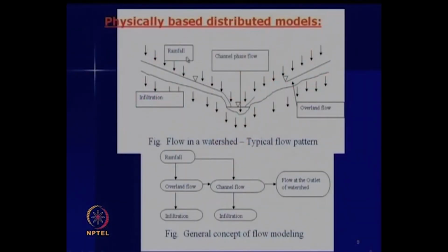So, now coming back to physically based distributed models, for example, if you are going for rainfall to runoff, depending upon the objectives, as I mentioned, we may consider only some of the important hydrologic processes. For rainfall to runoff in an agricultural watershed with event based modeling, we do not have to worry about the small quantity processes like interception, and even we can neglect the evapotranspiration.